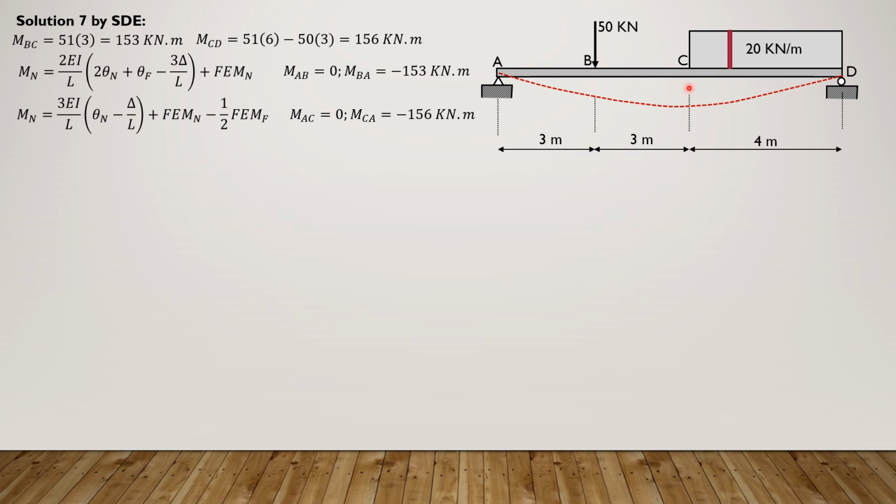Then because we anticipate that there's no problem with this concentrated load, we can write the fixed end moment formula only for this loading, which is at a certain segment only of the beam. So we consider a strip. The P here is 20 dx, that the thickness is dx, and because the height is 20 kilonewton per meter, it is 20 dx, the P. So we will call this x, and this is 4 minus x. So 20 dx, this is 4 minus x.